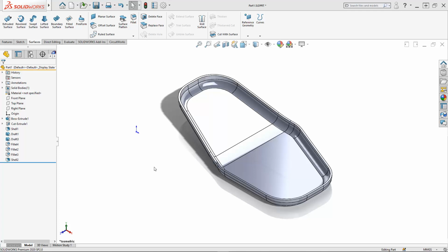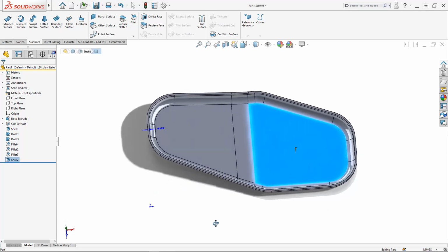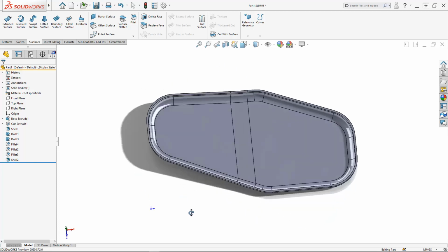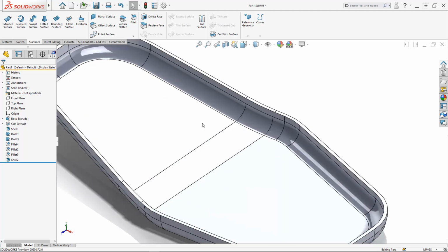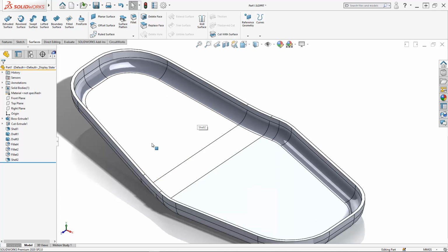So we had a problem come into our support line where somebody wanted to add constant width fillets onto a plastic component. This was for stiffening, and it was to sort of make it look like a waffle, sort of lattice arrangement. Okay, but we needed to include draft on this because it was going to be injection molded. So the pull direction was in this direction here, but we also came around a curved face and up at a straight line. So it was how to add the draft on this sort of lattice framework that we were going to go with. Okay, so let's see how we could go about this one then.